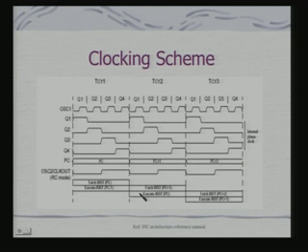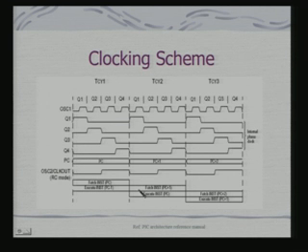In the next clock cycle, what am I doing? I am actually executing the instruction that I have fetched. Now, execution of this instruction would essentially mean what? In terms of bus demand, a data movement from your register file. That movement would take place on your data bus. So, my program bus is free, so I can fetch an instruction. What am I fetching? I am fetching the instruction at PC plus 1. Similarly, when I am fetching the instruction pointed to by PC, I am executing the instruction pointed to by PC minus 1. And this is how the instruction execution takes place, and what you really realize is that in one cycle, one instruction gets executed. Is this clear?